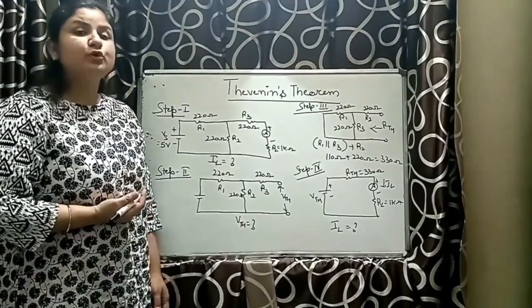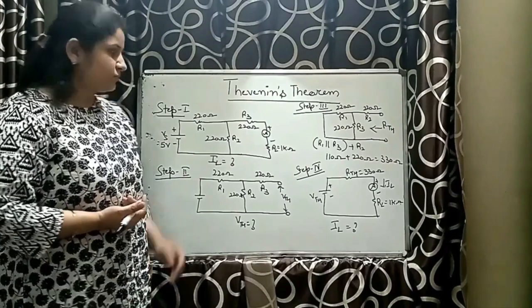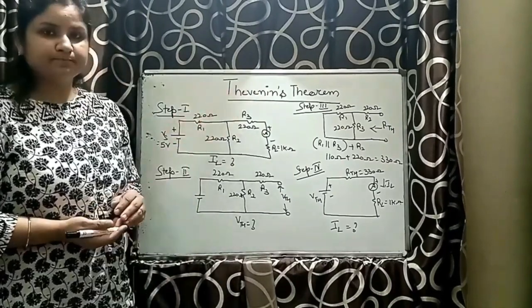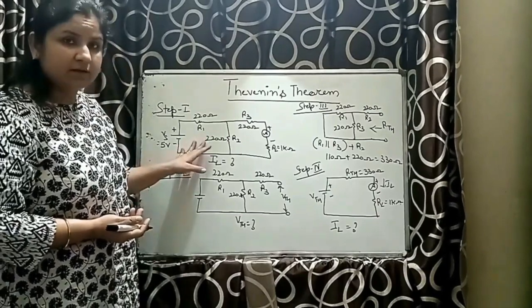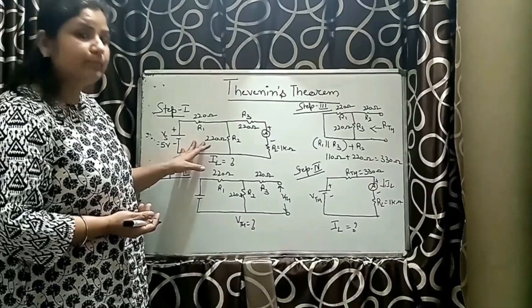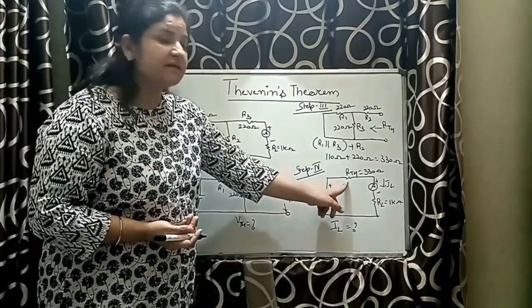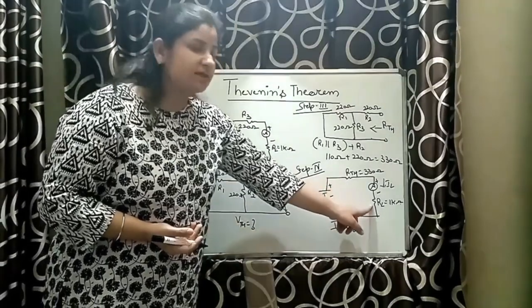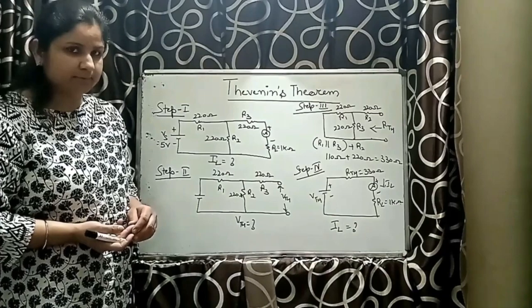In this video, I am going to talk about the Thevenin's experiment. Thevenin's theorem states that any complicated circuit can be redrawn as a simpler circuit in which we have VTH in series with RTH in series with RL. Now let us discuss how this practical can be done.